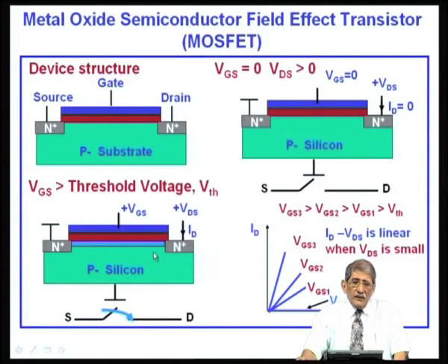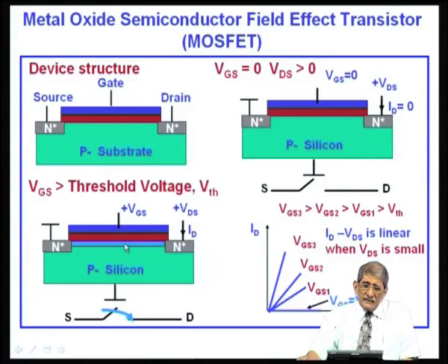Okay. So, you have a voltage drop across this, which is called the channel. Source, drain and the channel. Channel is the path created by this applied electric field, okay, and this path is created because of the negative charges, electrons. And so, there will be current flow from drain to source, because of net electron flow from source to the drain.